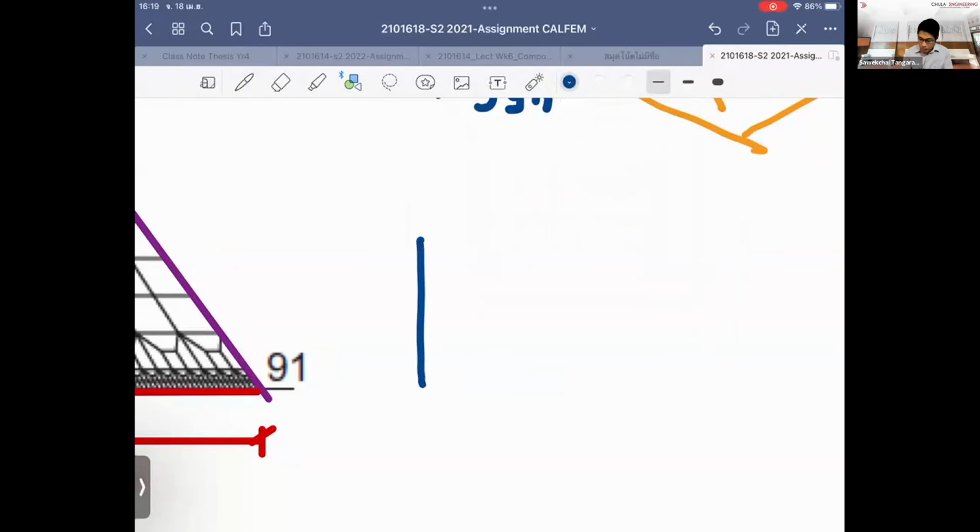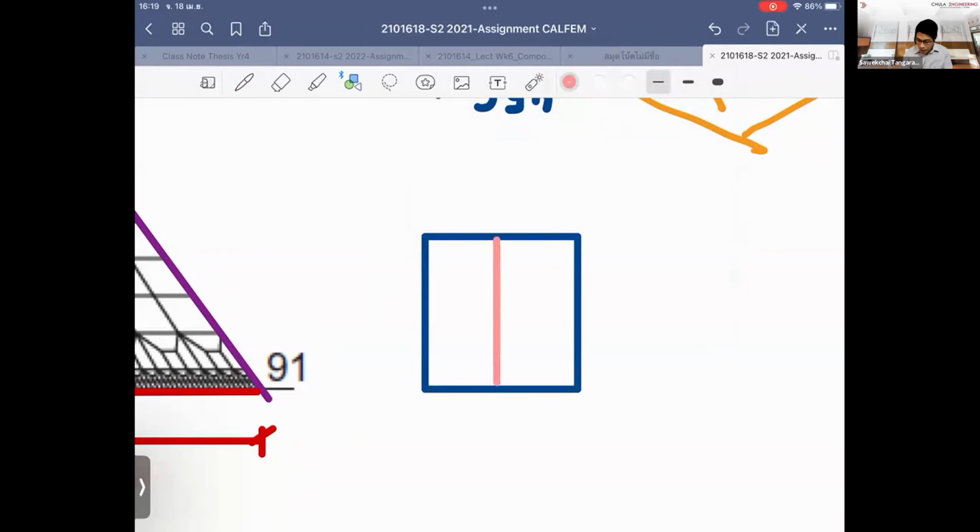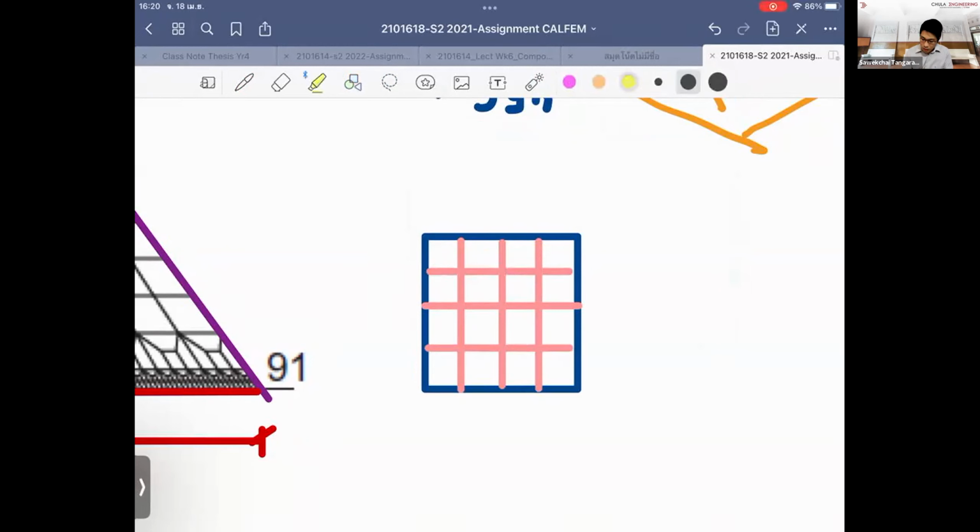So if I'm looking at the problem here, and I just try to run the standard structural discretization, so I just keep dividing by half, right? If I keep splitting by half and I keep doing this, and let's say I want to investigate the stress values at the bottom, knowing that the stress value at the bottom is critical, what I need is more meshes at the bottom.